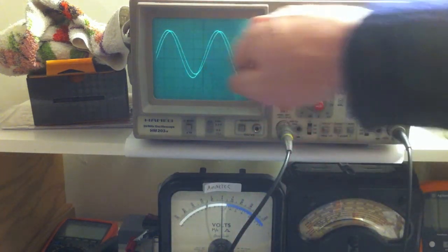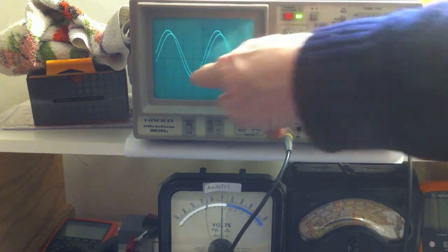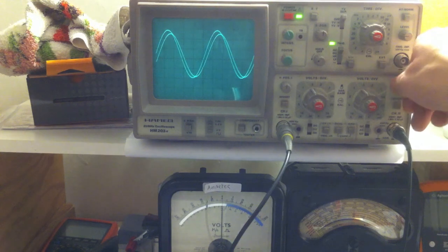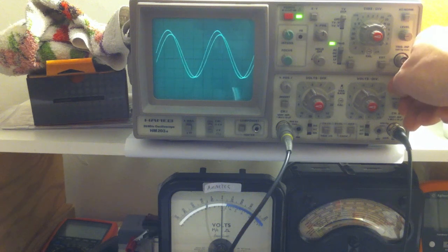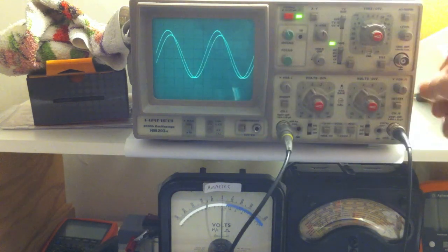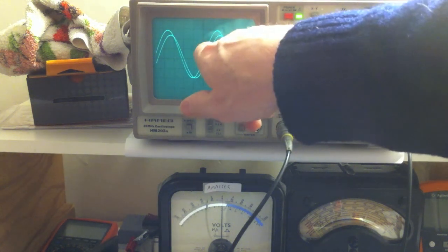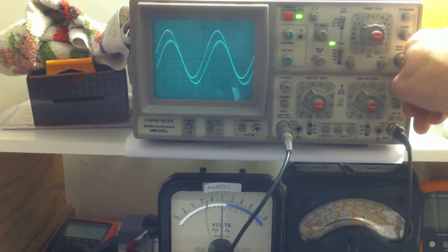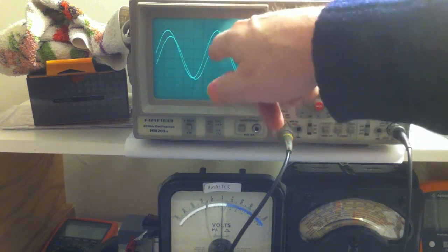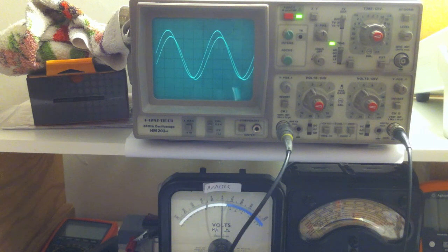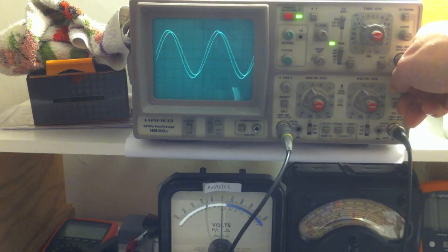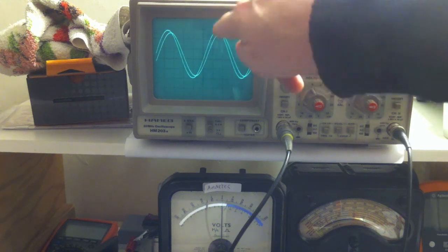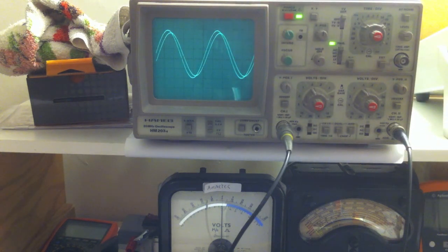It's negative, yeah. And then on the other side, from here to here, you can see the capacitor voltage is now lower than the input voltage. Because it's at a lower voltage than the input voltage, the charges are going to flow from the voltage in into the capacitor. So now they're going, if you like, in a positive direction. They're going from the voltage in, and they're depositing on the capacitor. And then if you carry on, this part down to here, they've swapped again. So that's what's going on.